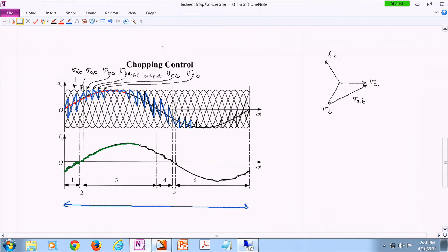So there are some sudden jumps in the input voltage, and that creates a little bit of a ripple in your output current. But overall, you can argue that your output current is a good quality, low frequency AC signal. So we achieved the goal that we were trying to do: use a matrix converter and the simplicities associated with it, and generate a current that is almost AC low frequency.